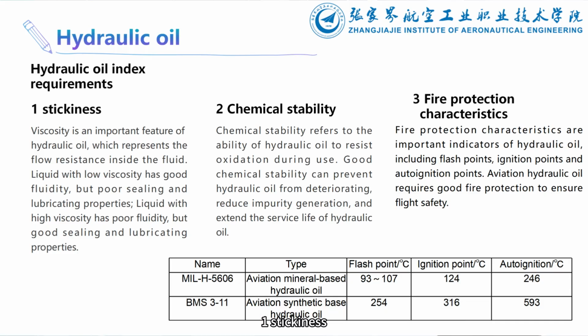1. Viscosity. When a fluid moves, it generates internal friction due to the cohesion of the molecules, which appears as viscosity, also called stickiness, and a stationary fluid does not show viscosity. Low viscosity leads to seal failure and wear. Too high, it increases resistance and temperature rise. Viscosity is divided into dynamic viscosity, kinematic viscosity, and relative viscosity, which need to be measured by a viscosity meter.